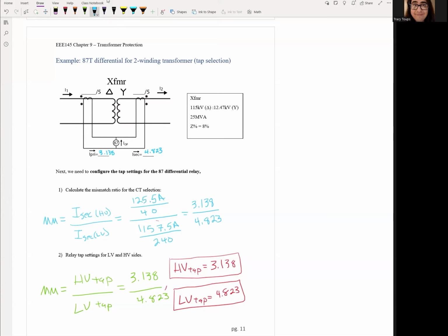And the relay is smart enough to do the division for us to find the actual ratio. So from this point on, this is how we correct all that CT mismatch, and based on the CT ratio chosen, your relay should act pretty well accordingly now.